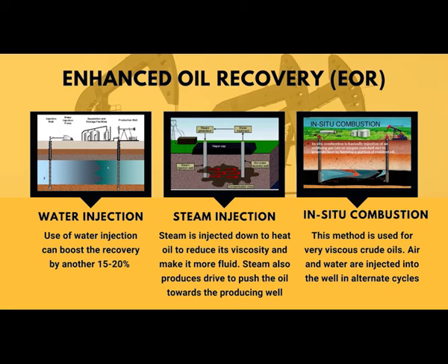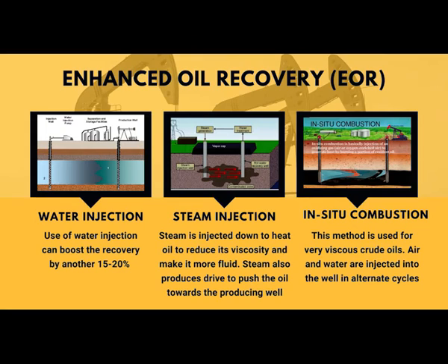The second technique, steam injection: instead of water, we are now allowing high pressure steam. This is employed where you come across highly viscous oil. This highly viscous oil is getting diluted by admitting the steam. The steam is melting the oil, and the viscosity of the crude oil is reduced, and that helps the pumpability from the bottom of the earth to the upper surface. The third technique, in situ combustion.